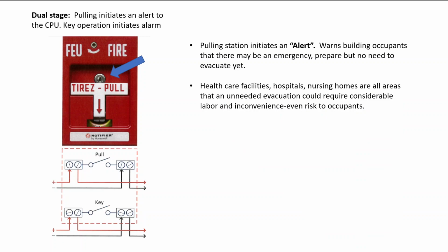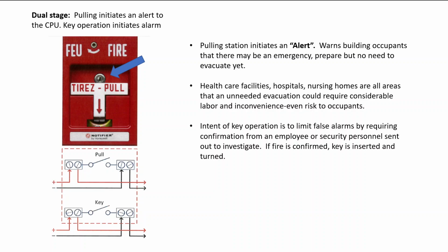Healthcare facilities, hospitals, nursing homes are all areas where an unneeded evacuation could require considerable labor and inconvenience, even risk, to the occupants. The intent of the keyed operation is to limit false alarms by requiring confirmation from an employee or security personnel sent out to investigate. If a fire is confirmed, the key is inserted into a pull station and turned.